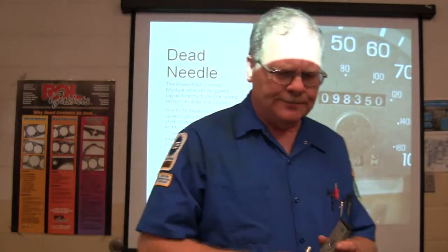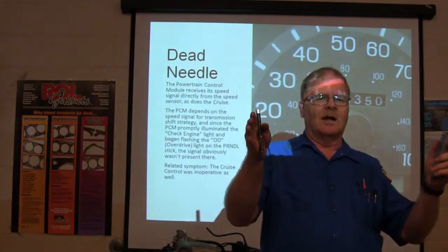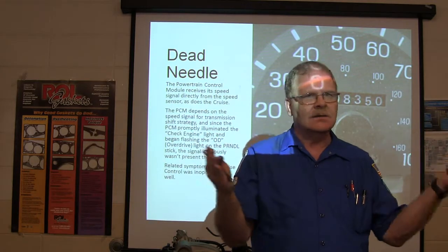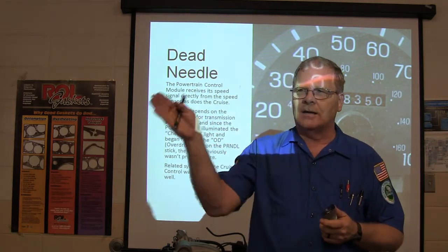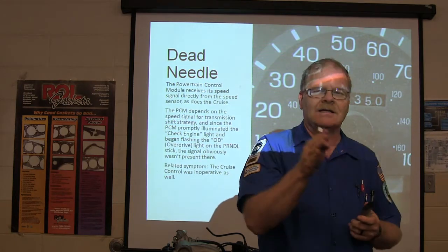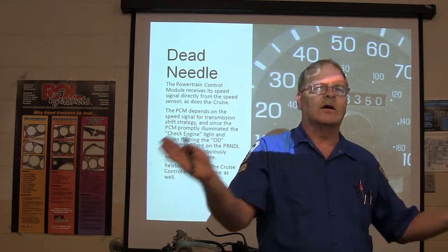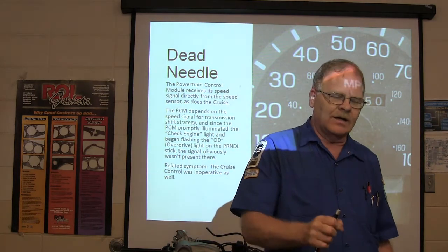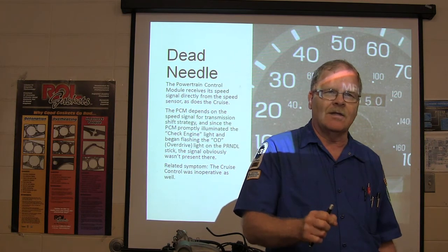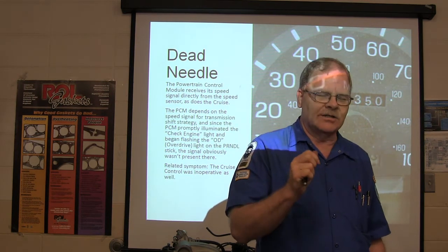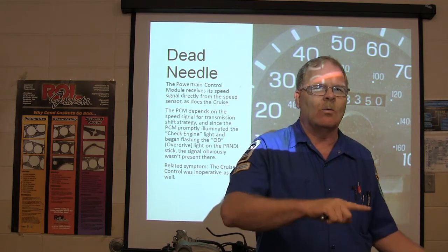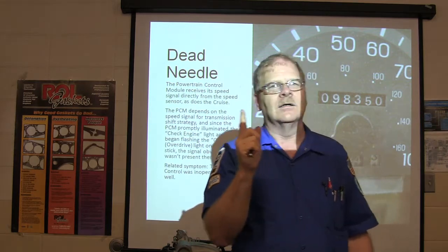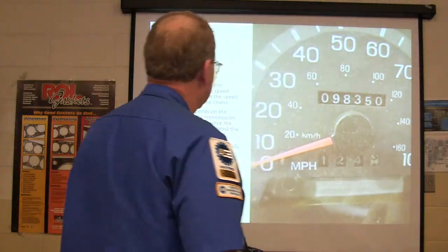Here's the thing you need to do. If you're looking at an electrical problem, you need to see if there's anything else that may be related to it. You know what I mean? Check other things. Because a lot of the time you can draw yourself a picture in your mind and say, okay, this is not working, that's not working, that's not working. What do all those have in common? Like for example, there was a car I used to have here, and there was one little ground wire I could take loose on that one car. And not only would the scan tool not talk, the car wouldn't start, and the wipers would run all the time when you turned on the key, because of one little ground wire. So be really particular about that kind of thing.